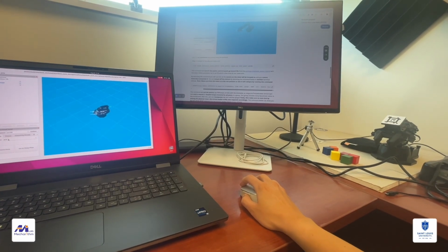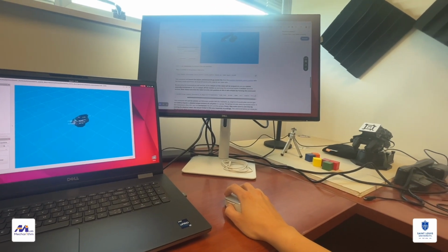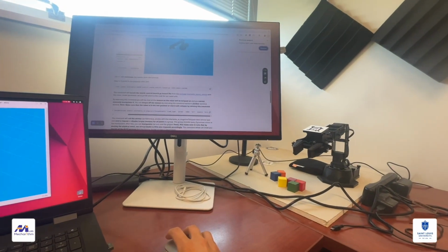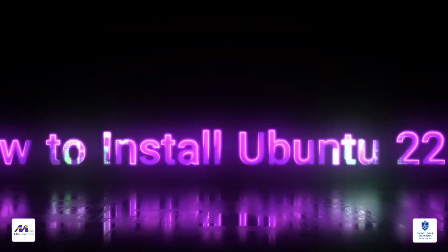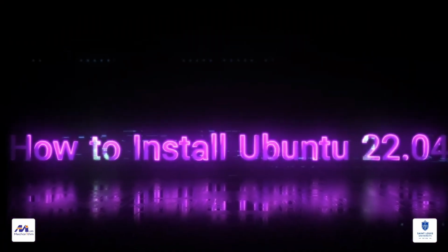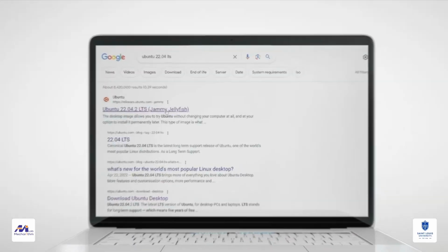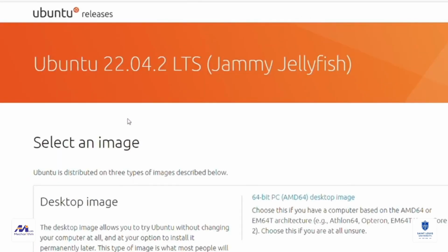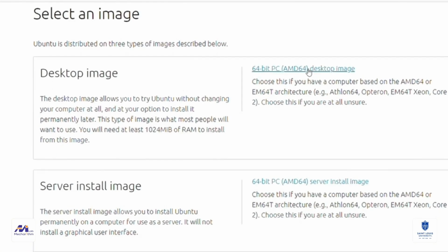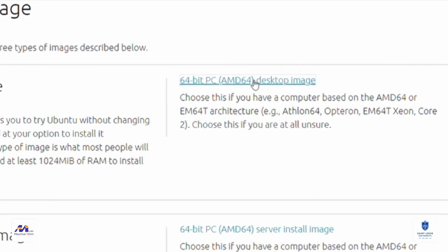In this activity, our primary objective is to install both ROS and Python ROS interfaces to be able to control our robot arm. As our intention is to use ROS2 Humble, we have already taken the necessary steps to set up Ubuntu 22.04 in the previous videos. It was essential to select this specific version of Ubuntu since ROS distributions are OS specific.